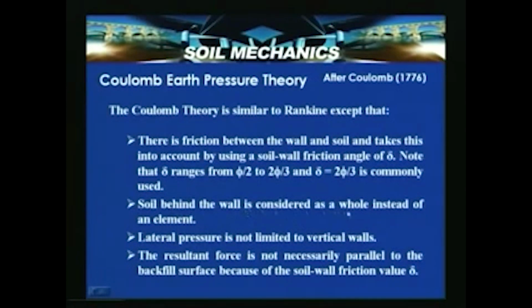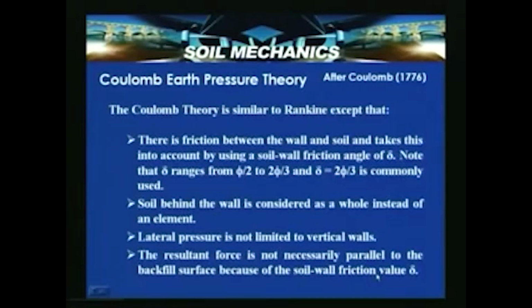Then the soil behind the wall is considered as a whole instead of an element. And lateral pressure is not limited to vertical walls. You can have a wall with any inclination, and the backfill surface can have a slope, need not necessarily be horizontal. And the resultant force is not necessarily parallel to the backfill surface because of the soil-wall friction value delta.